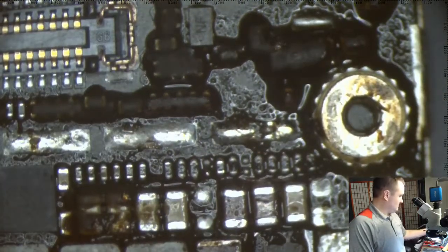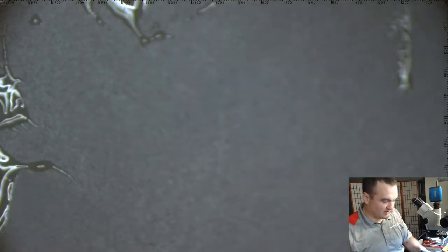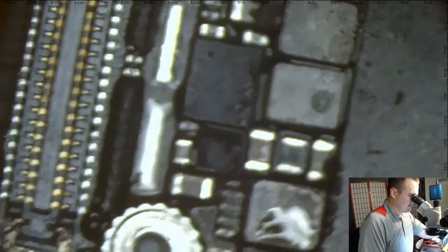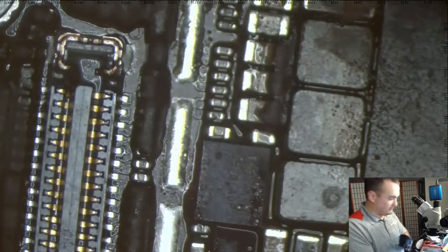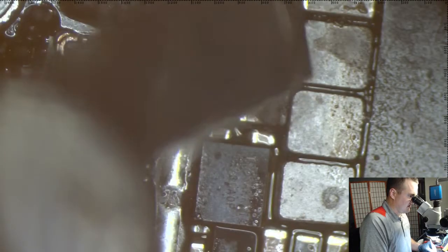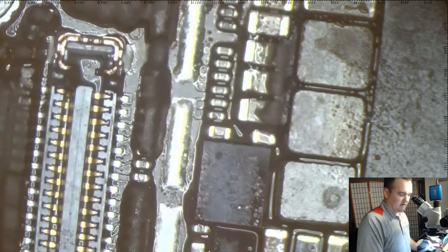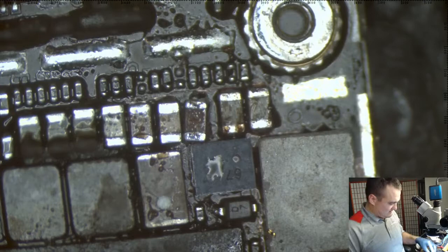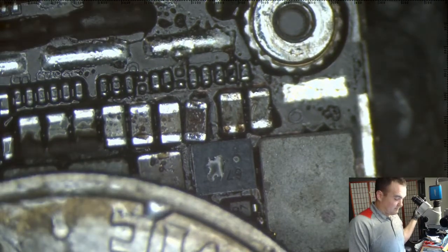But I wouldn't bet on any unrepaired iPhone 7. I would not bet that it won't show audio IC issues in the next 90 days. I wouldn't do it. Same thing with the 6 Plus. If you buy a 6 Plus from somebody and it's never had Touch IC repaired, you better go ahead and do your M1 jumper before reselling it. That thing's going to come back.